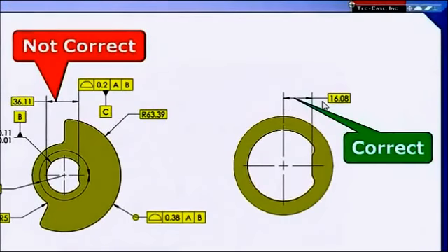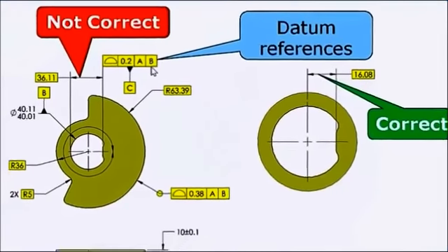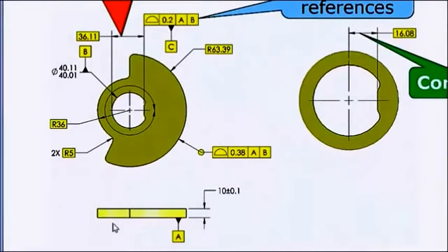This would be correct. If we look at the profile tolerance, it tells us that the profile is located with respect to the datums established by features A and B. So A is this face down here, and so that would give me a datum plane. And then B is this diameter, and that gives me a fixed axis. And since B is regardless of material boundary, the old regardless of feature size, whether this diameter comes in large or small, we're to center up and get that axis.